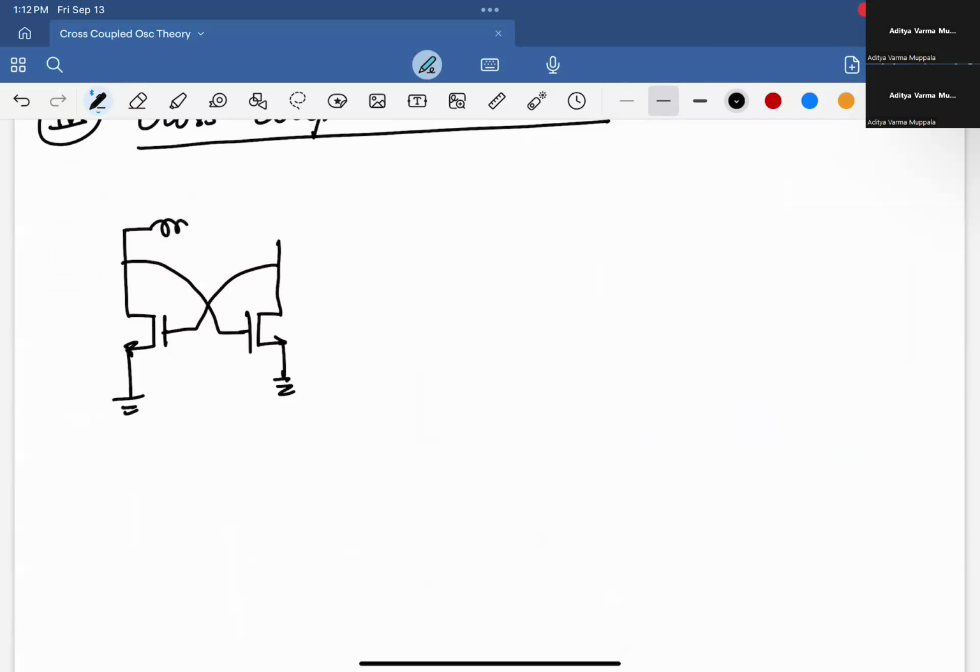And then we have, let's say, an inductor and its series resistance. So this is the actual model. And then a capacitor like that, right? So that's kind of the starting point. So this is L, S, R, S, and some C. And we just saw how to convert this into a parallel model, let's say at the oscillation frequency.